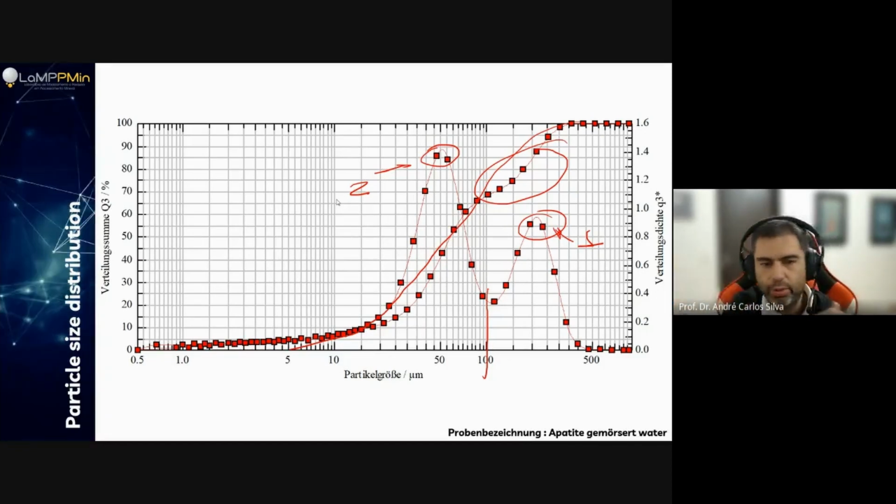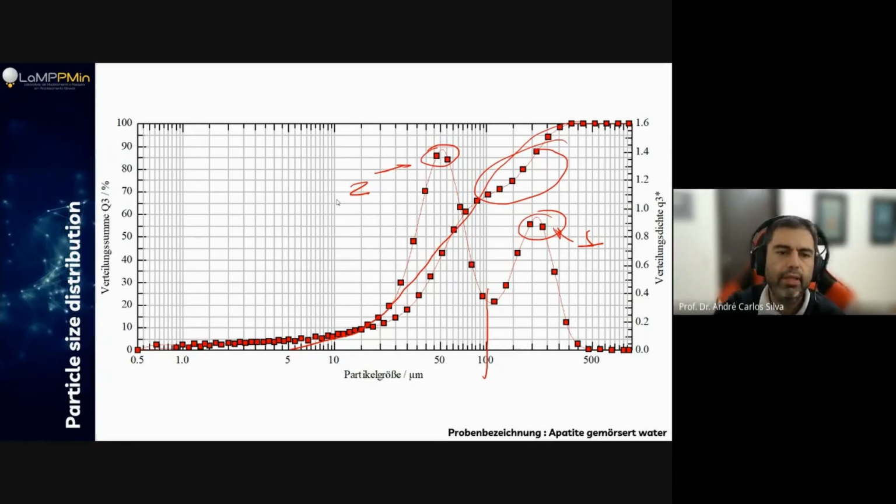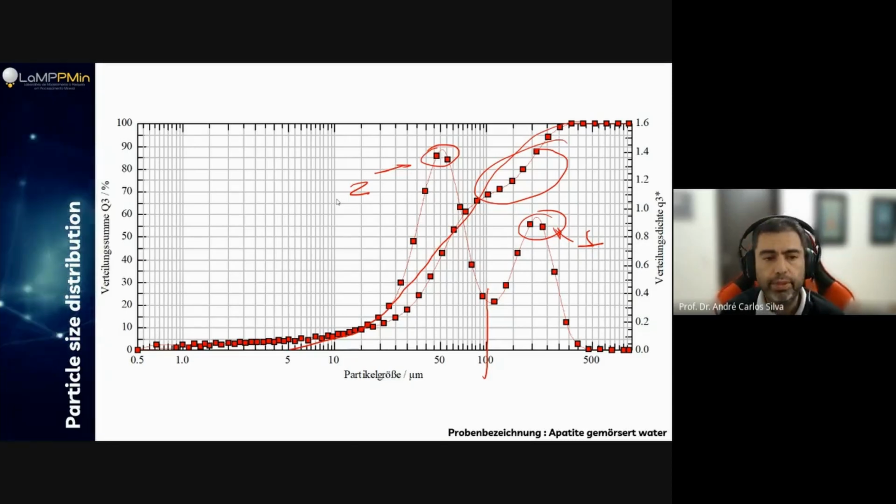And then you just throw away the fines and keep just the coarse particles, and then you go to a mill with this coarse fraction, and then you keep grinding, and then eventually you go to concentration. But yes, you can have a pre-concentration of your material by doing a screening, okay? By using classification to do this, and it works pretty good. Okay, thanks. I'm not sure if I answered your question, but if that's the question, yes, you can use this information in order to enhance your capability to process your material.